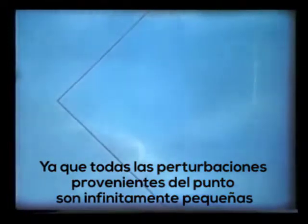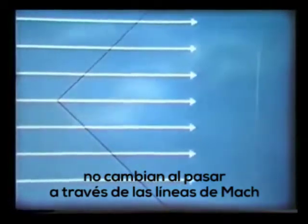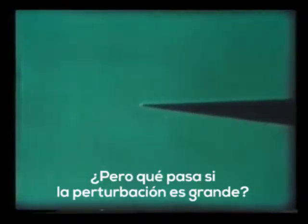The water outside this region flows on as though no disturbance existed. In the same way, the supersonic point can only affect the air lying inside the Mach lines, shown here in white. Ahead of the Mach lines, the air is undisturbed. Since all the disturbances coming from the point are infinitely small, the speed and direction of the airflow, shown here by white streamlines, don't change as the air passes through the Mach lines. But what if the disturbance is large?